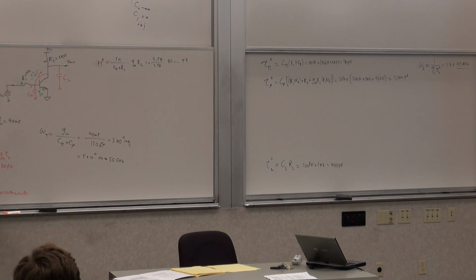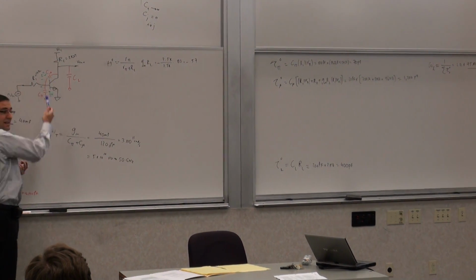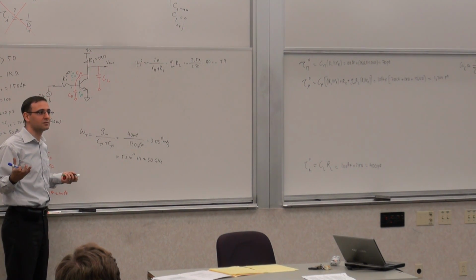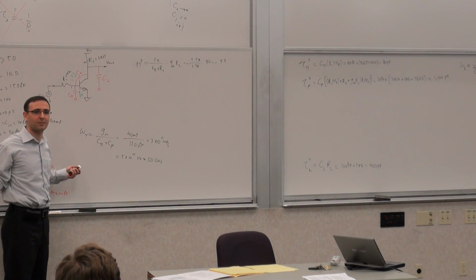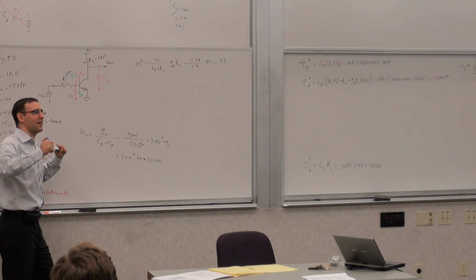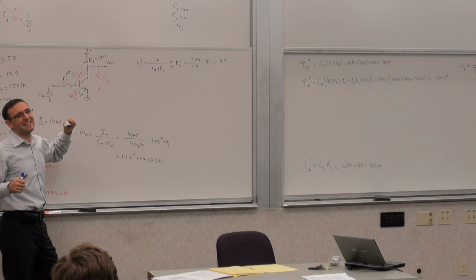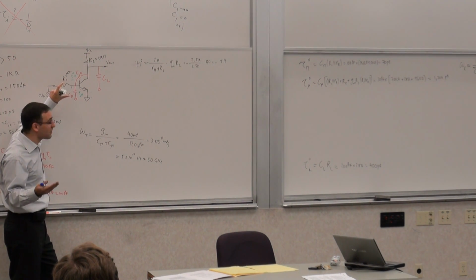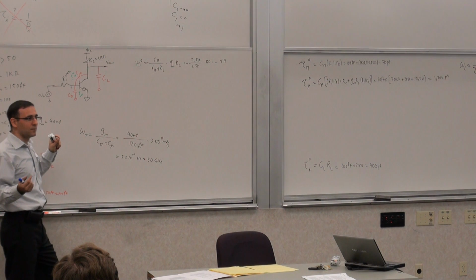Well, we can't eliminate this capacitor, right? The capacitor is part of the transistor. It's part of the junction. If you have the junction, you have the capacitor. You can say, okay, I can bias it slightly differently, I will get a different capacitance, but yeah, those are incremental improvements. What can we do that's substantial, topological?